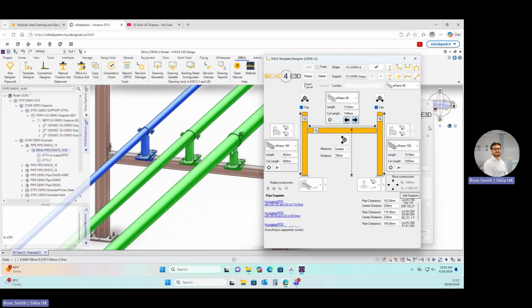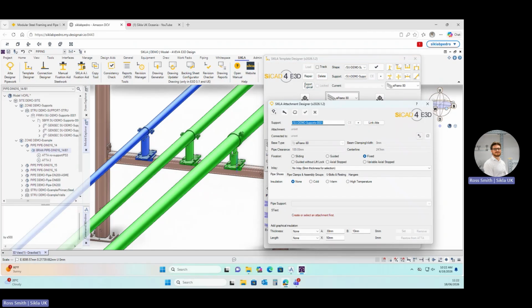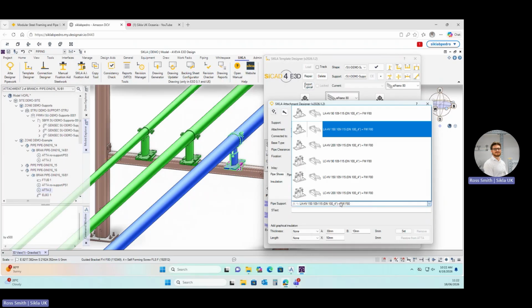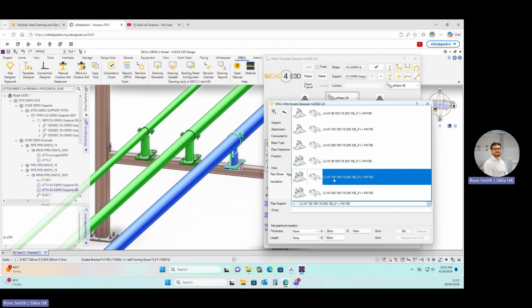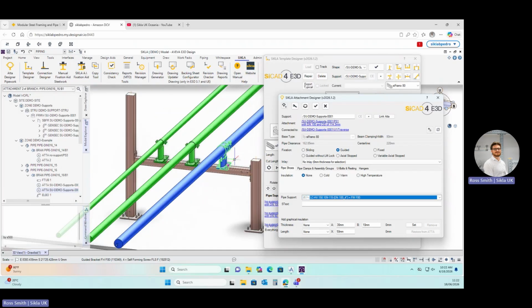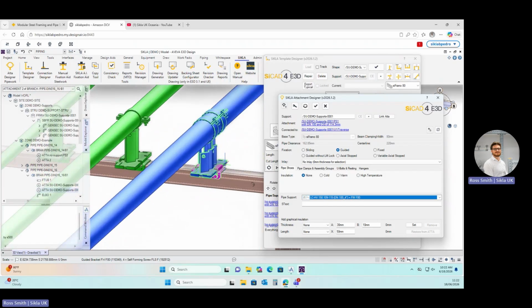And then after this, we can manipulate any of these to something else. Okay, maybe I need the double pipe clamp plus a guide in this situation. Okay, or perhaps a pipe shoe. This may be just a cold pipe without the need for a Sikla pipe shoe and an industrial restraint.